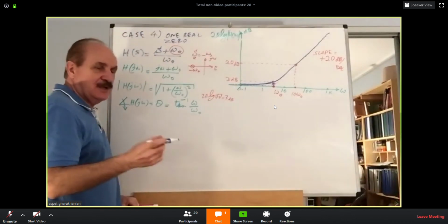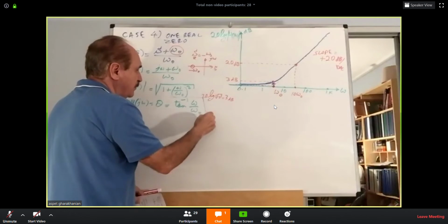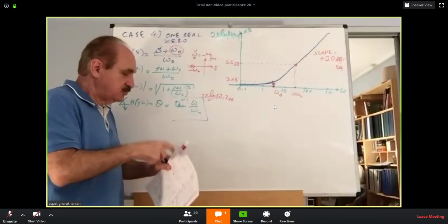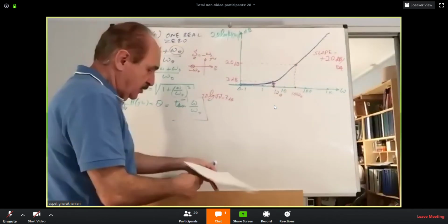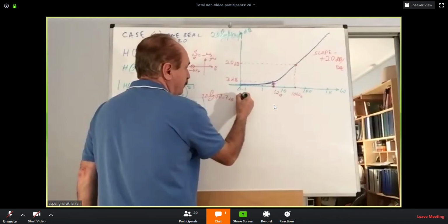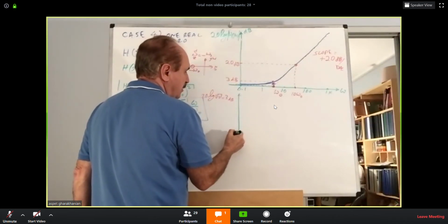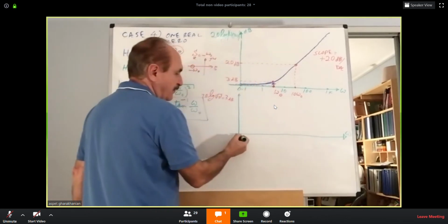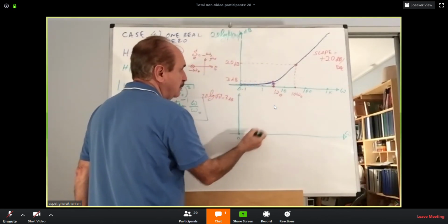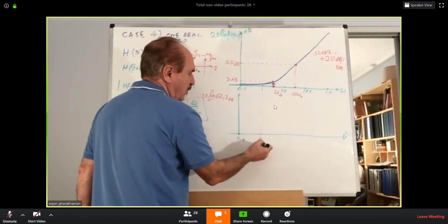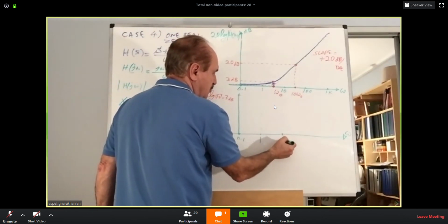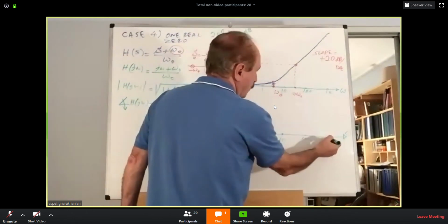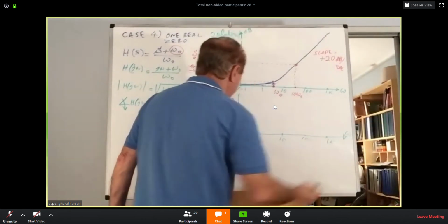That was the magnitude. Now check this one out. How do we plot the phase angle? Okay, let's see what tools we have. You will construct your logarithmic scale, omega versus the logs of frequencies: 0.1, 1, 10, 100, and 1K radians per second.